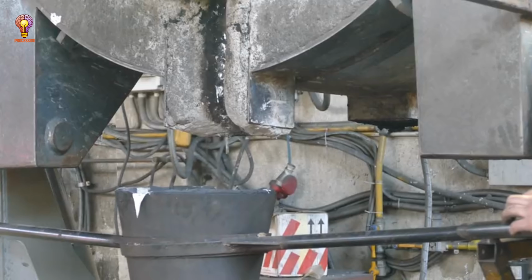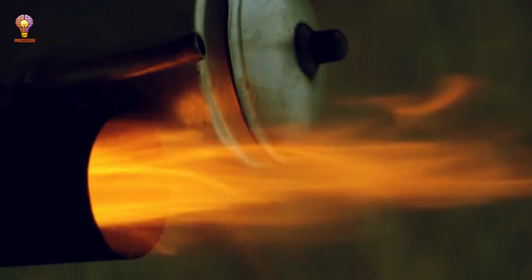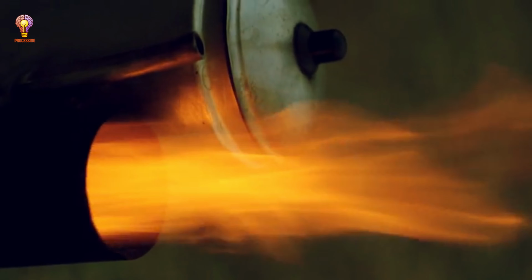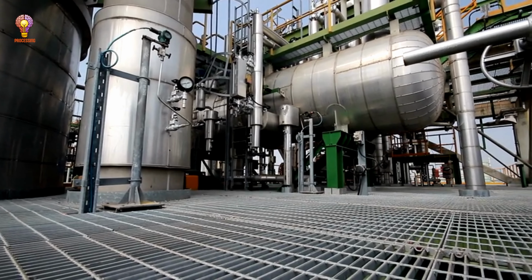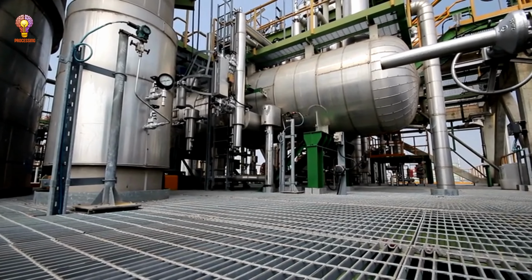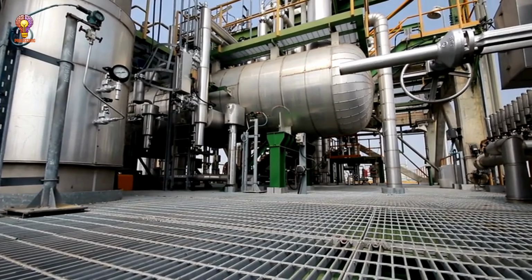Ladle refining. This process takes place in a ladle, a large refractory-lined container, where various adjustments are made, such as temperature control, deoxidation, removal of excess oxygen, and alloying. Gas purging with inert gases like argon helps homogenize the molten steel. Vacuum degassing. This process is used to further reduce the levels of dissolved gases like hydrogen and nitrogen, which can negatively affect steel properties.